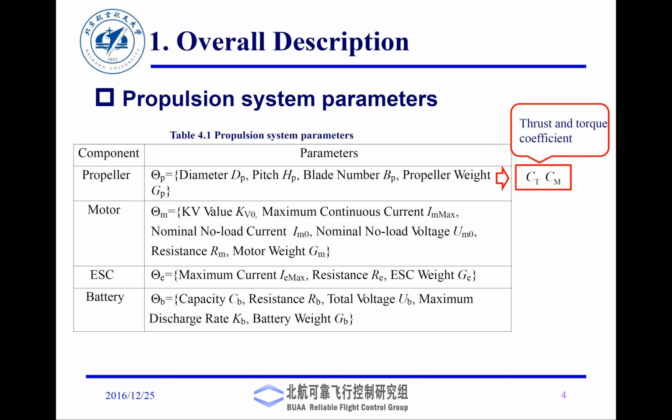The ESC is basically the electronic circuit board, and the way it works is it will have MOSFETs, which are like switches. You turn them on and off very rapidly so that you excite each winding in a certain sequence that would make the brushless DC motor rotate.